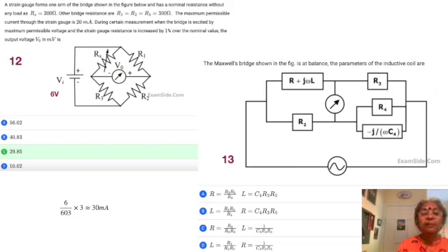Okay, for the 13th problem, we have a complex structure, but it's very simple because we have resistive and reactive components which can be equated separately. On the right hand side we have a parallel structure of a resistance and a capacitance, which is even better. Why? Because we should know that R2 into R3 divided by R4 will give you R, and R2 into R3 divided by 1 by omega C4 will give you omega L. So let's see what the problem is.